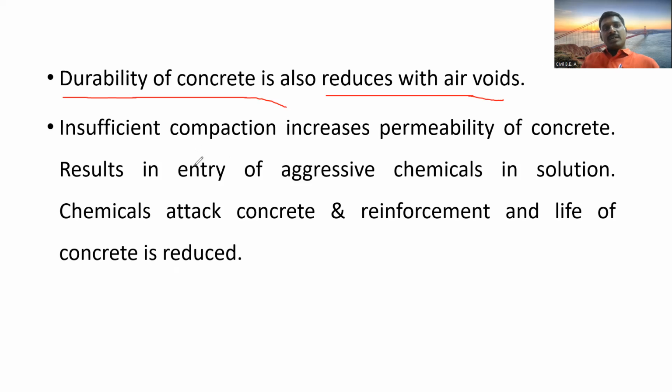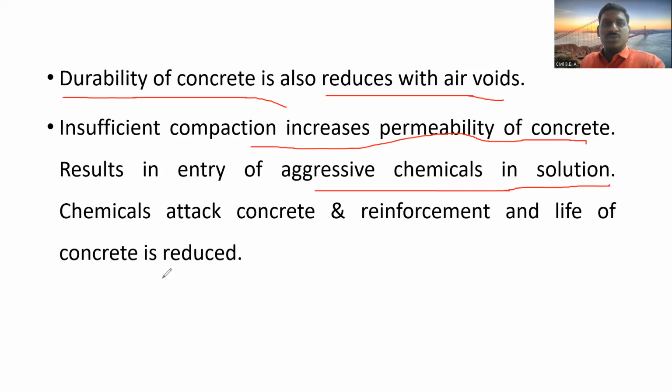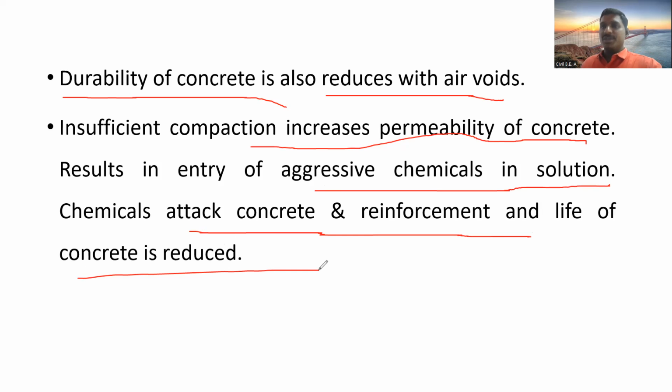Then insufficient compaction increases the permeability of concrete as well. The result is aggressive chemicals in solution, chemical attack on concrete and reinforcement, and reduced life of the concrete.